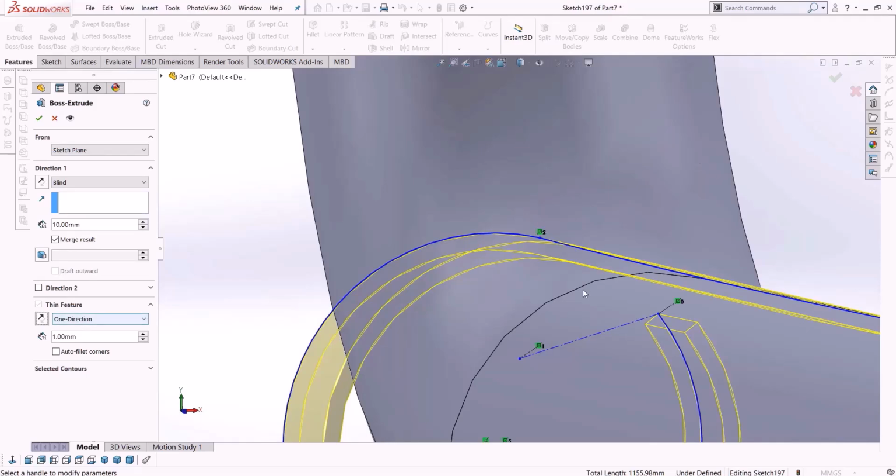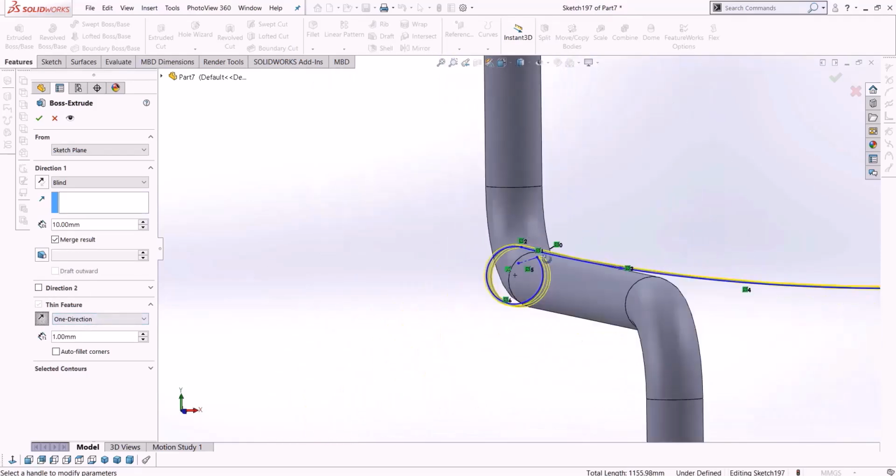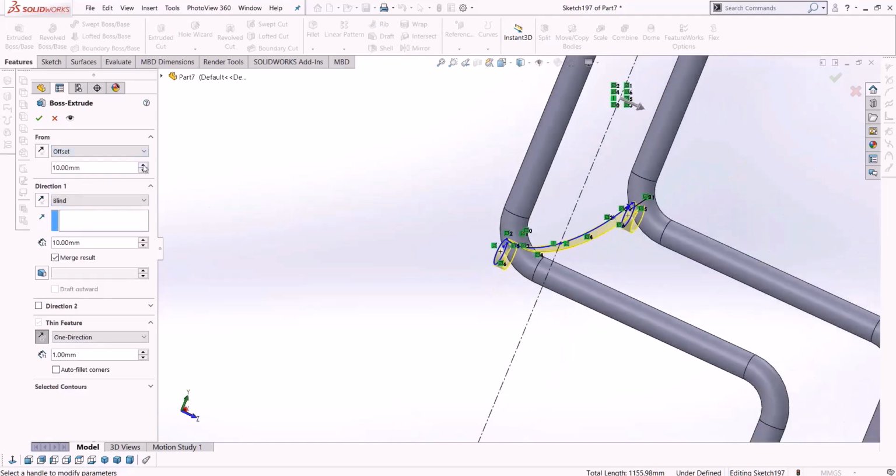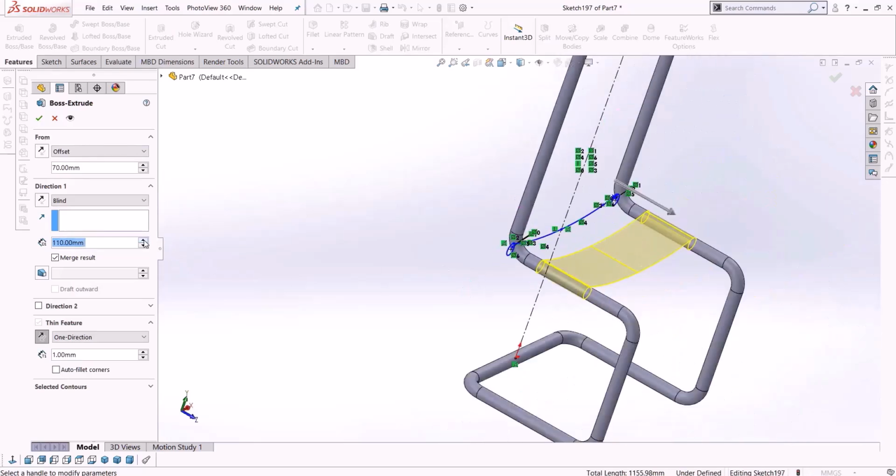You see, from this line going up, or inward, since I made it very close to the rod, I say outward. But where did it start? From that front plane, which is unacceptable here. Remember that we were allowed to say to start the extrusion from a specific plane that I introduced to you. The last option, the offset option, tells us to move 70 millimeters forward, parallel to the same front plane that I started from, effectively starting from the sketch. Now I will perform my extrusion.